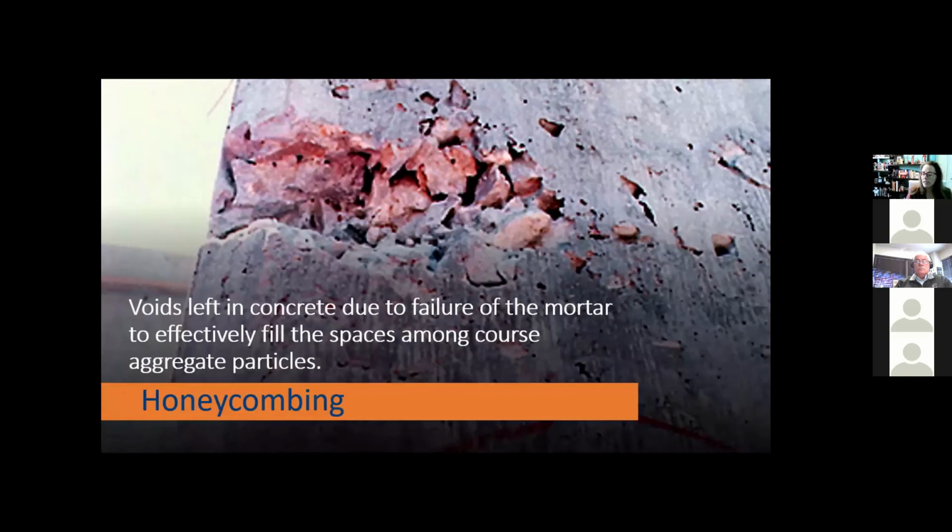It sounds so simple. It's just a failure of proper consolidation, and so you get some loss of paste around aggregates. What's the good news here? You can see it. So if you can see it, you can repair it. What's the bad news? Now I question the rest of the structure. I want to know how the interior of that concrete is. Uniformity matters, consolidation matters, but I wouldn't only blame the contractor here.